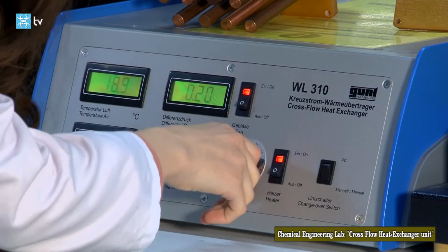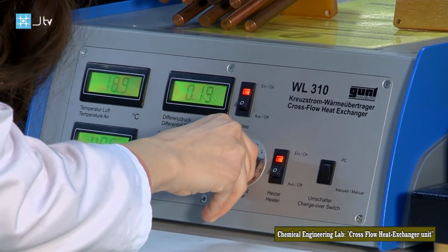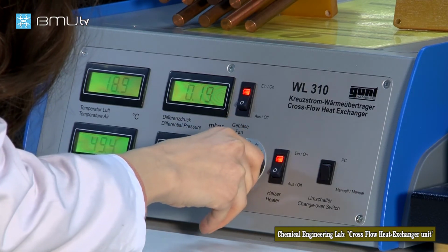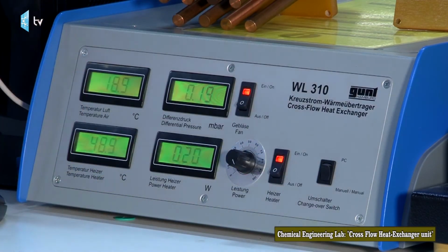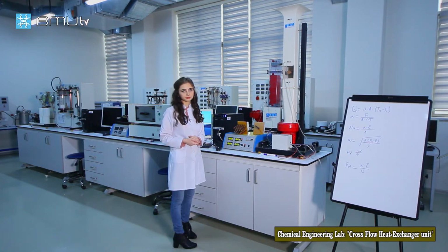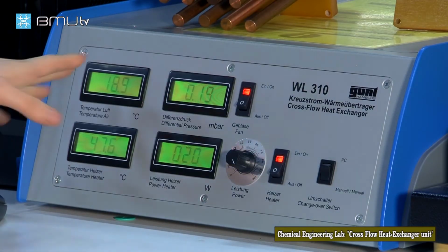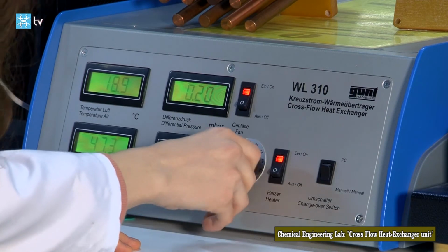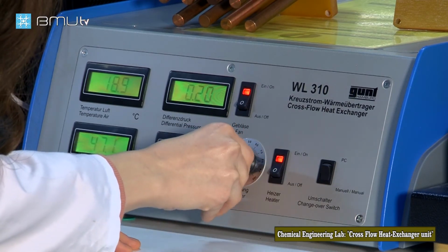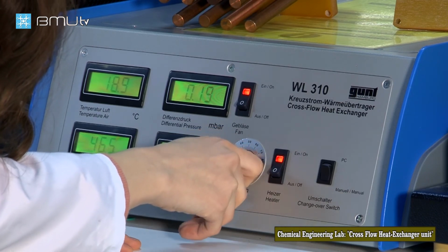So you'll indicate the temperature. And next, again, we'll change the power to 20 watt, as we did previously for the single pipe. Again we'll wait some time for the temperatures to reach steady reading. Let's wait. When it reaches the steady reading, we'll take the data and record it, and the next step we'll change the power to 33, as we did before for the previous heater element.